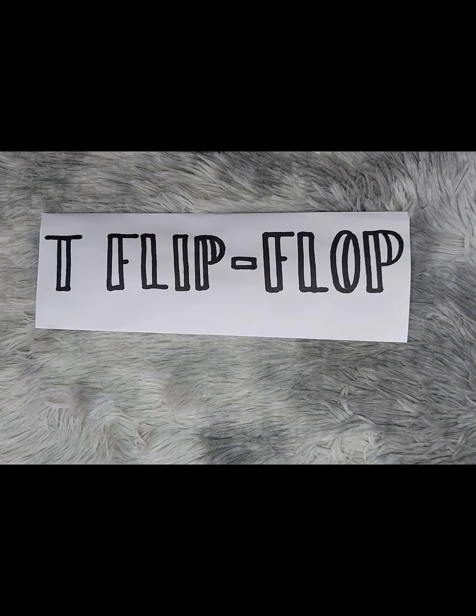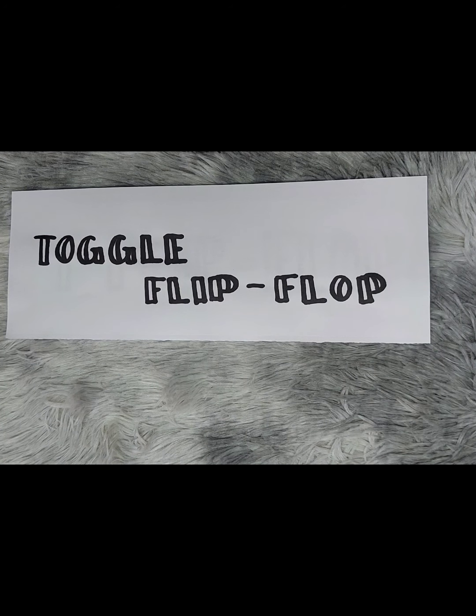T flip-flop: a clock flip-flop whose output toggles. Example, it changes to the complementary logic state on every active transition of the clock signal. The device acts as a divide by 2 counter since two active transitions of the clock signal generate one active transition of the output. The T or toggle flip-flop means the output will change with respect to the input along with the clock signal.